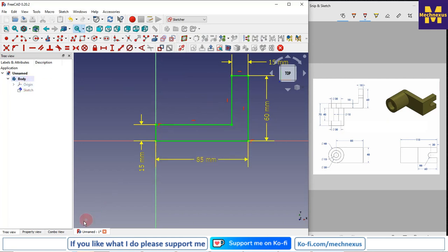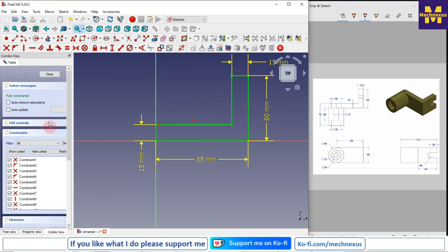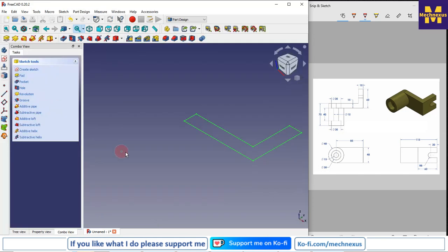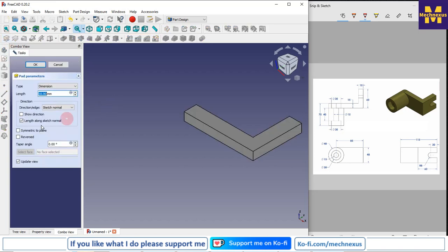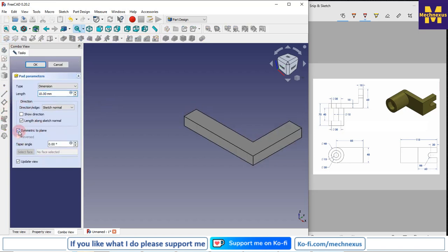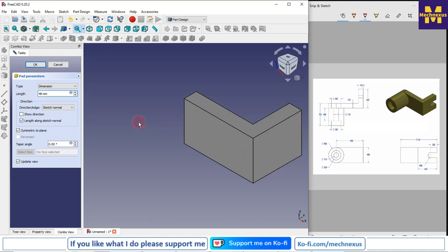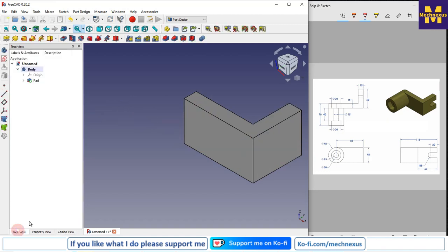Now I will come out of the sketch and then I will extrude it. I will take it symmetric to the plane, and total extrusion length is 48, which we can see here. So, okay, and now we will make the cut.